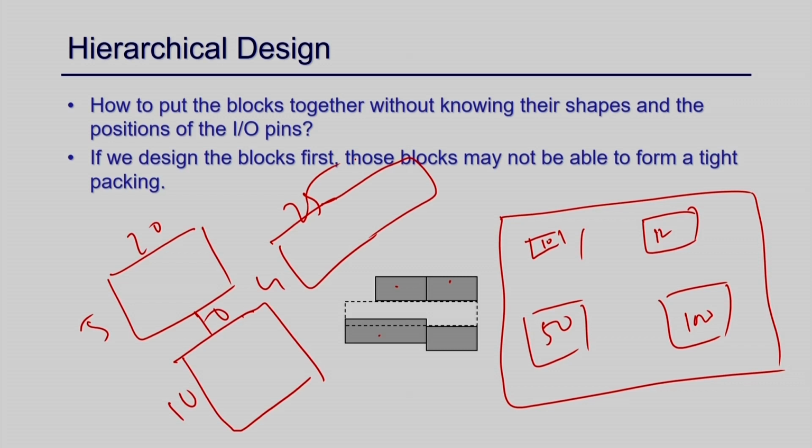You can have a different aspect ratio, because I just told you I have a block which has only 100 units. So now you have to fix this aspect ratio: for 100, should I choose 10 into 10, or is 5 into 20 better, or is 4 into 25 better, and other options are also there. So you always have to decide the aspect ratio of each component based on their total area, so that you can compact all the components in the minimum possible area.